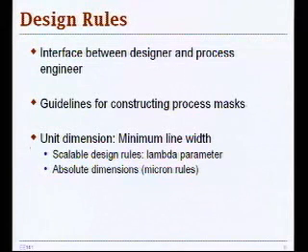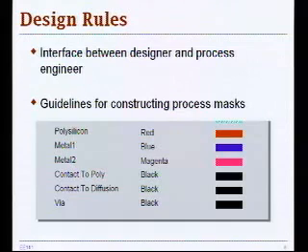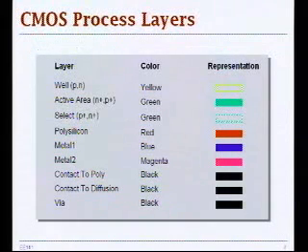So there is a couple of things that you really need to know to be able to design layout, and that is what process parameters do you have in terms of what layers do you have and that you can work with, and also spacing rules between these layers. So it's first important to understand the palette. And in pretty much any process, there is a couple of fundamental layers that I would like to emphasize here, and then we'll talk about the layers that will be available to you in your quarter-micron CMOS process.